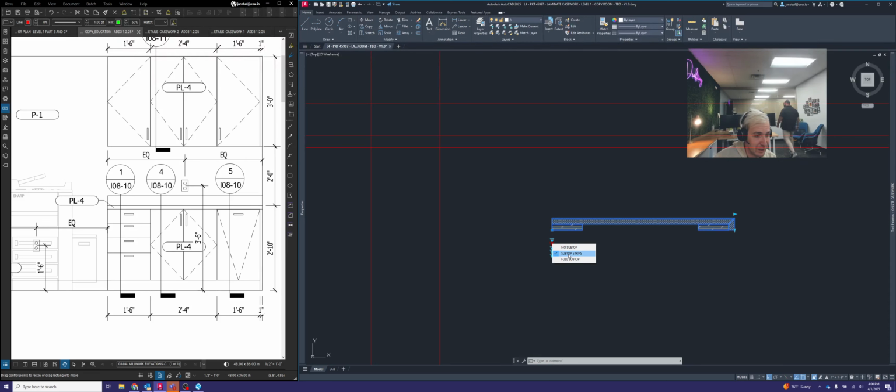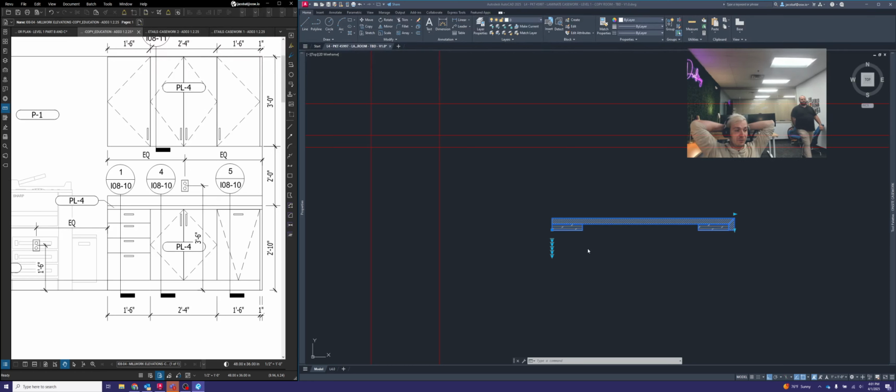All right. Some other things to talk about too. We can still use subtop strips. We only really use a full subtop when you're dealing with a large span, something that is about 36 or 48 inches wide. You'll probably want a full subtop for that to make sure that your countertop is being fully supported, and that's if there's nothing below that counter.